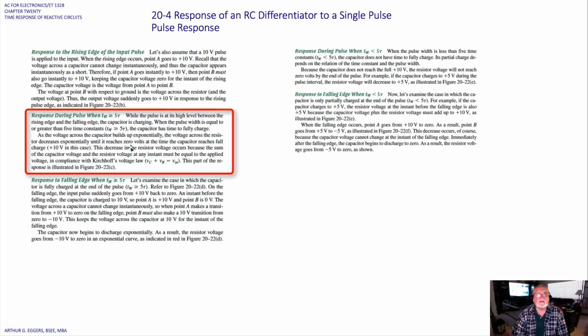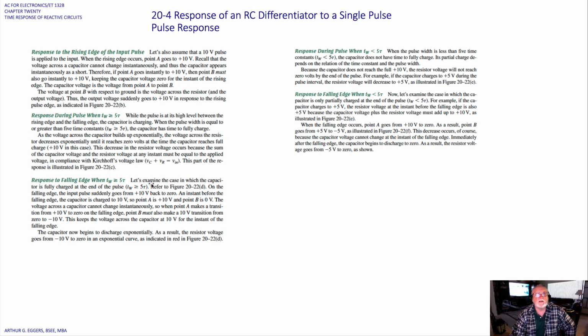This decrease in the resistor voltage occurs because the sum of the capacitor voltage and the resistor voltage at any instant must be equal to the applied voltage. This is in compliance with Kirchhoff's law. So V_C plus V_R equals V_in. This part of the response is illustrated in C. So now we move on.